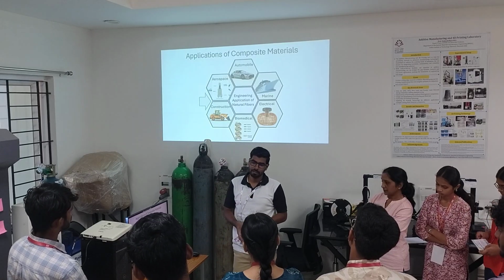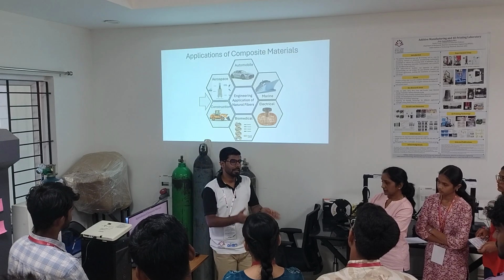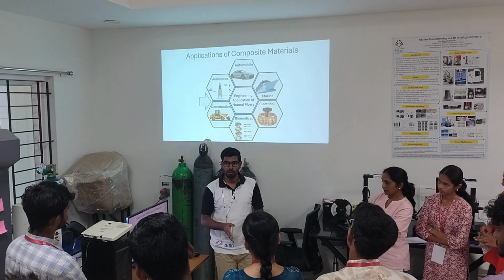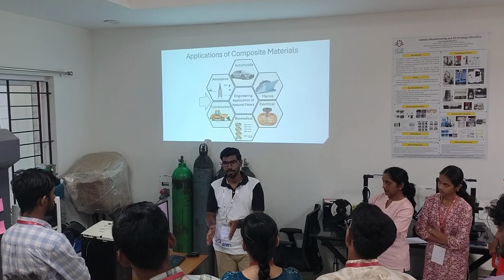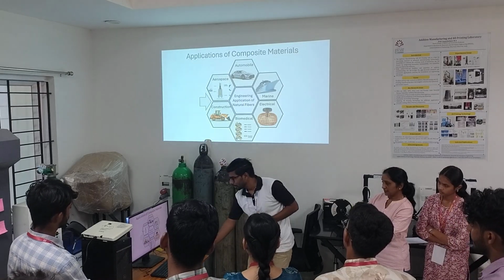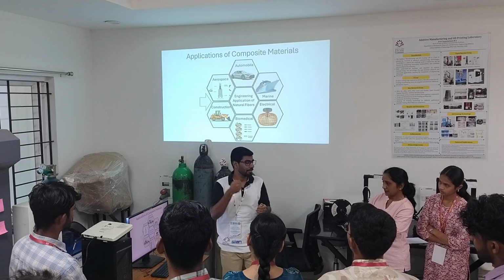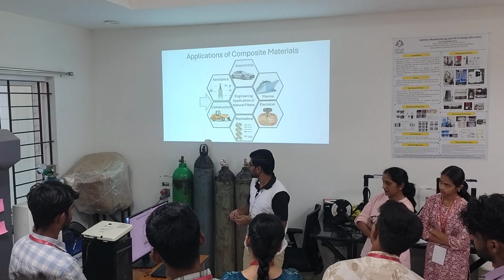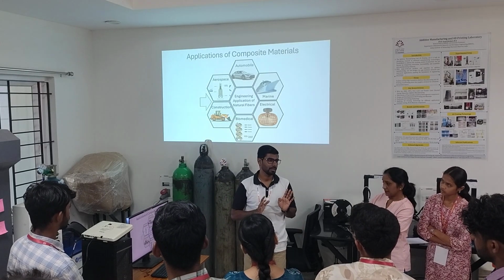Later on, while I was there for 1 year, within that time period itself, it was proposed: why can't we go for CFRP? And now half of them are made with aluminium 2024 and half with CFRP, carbon fiber reinforced plastics. Before, different panels were riveted together, but now it is a single whole body with just one CFRP.